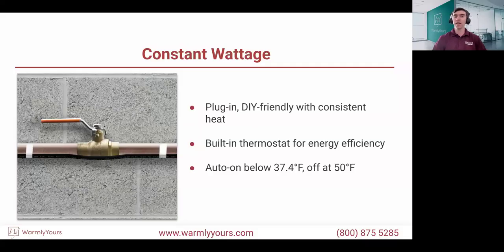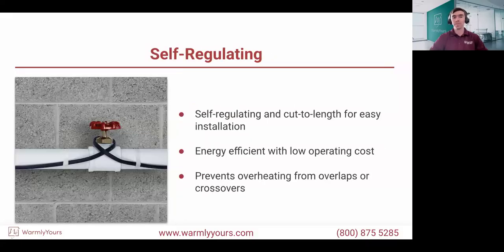You never should just apply the heat tape, I'm already using different terminology, heat cable, and leave it exposed, just taped to the pipe, because probably only 10-20% of that heat is going to make it to the job instead of 100%. So a very important factor. You're going to see that in the future slides, but I just wanted to point it out because these visuals show the inner workings halfway through the install.